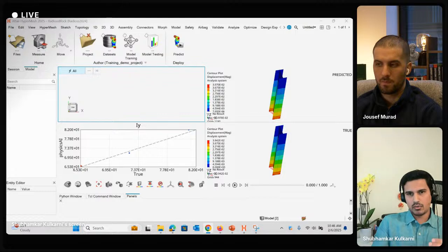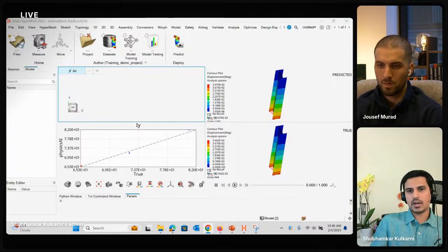Now, of course, you can always increase those hyperparameter values, but it is directly constrained by the memory available to you. In case you're not able to produce a good model in a single go, what you could do is maybe use transfer learning, or take out parts of the model which are not required. For example, let's say you've got an assembly of 20,000 parts, but you're really focused on two or three critical parts, and the other parts are not really contributing so much, like bolts and nuts. So you can remove those and really keep a razor focus on the objective.